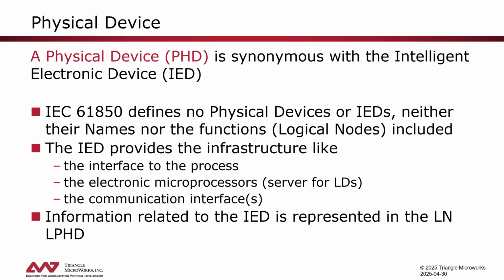As such, we may also have information for our SCADA system related to the IED, like when we have a problem with a power supply or whatever. And for that, we have a special logical node that we call the LPHD. So this is really the information now related to the IED.